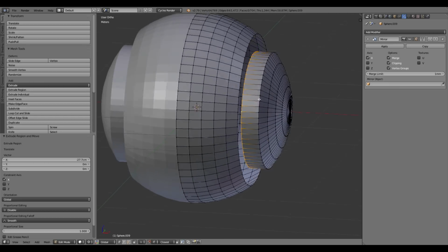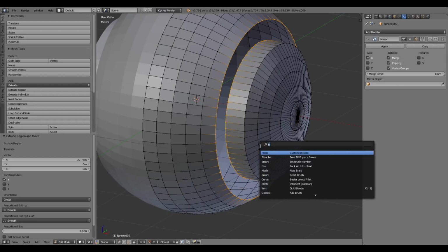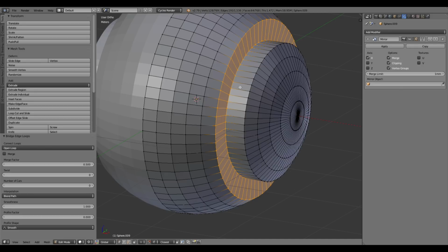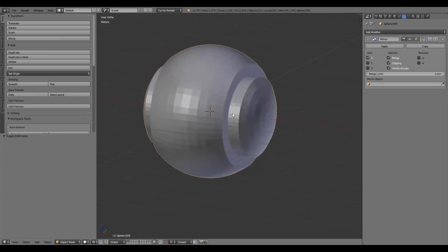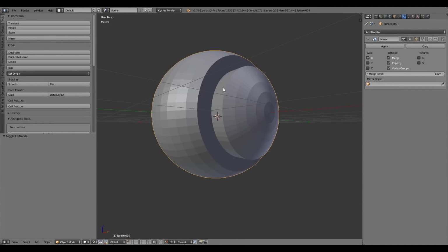You click there, and what this means is that these vertices and these vertices are now on exactly the same plane. So if I went Shift, Alt, Select here, I've got two rings selected. And by hitting spacebar, I'm going to type in bridge edge loops. Suddenly we fill in those faces evenly and our edge loops are conserved. Okay, so that's one way that you can sort of cut out a segment of something like a circle to make a more complex shape.